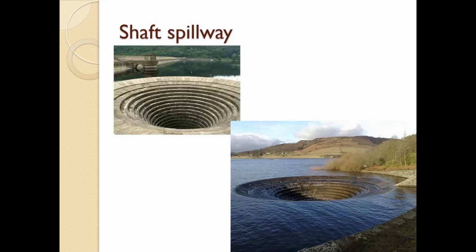The discharge through a shaft spillway does not increase at such a high rate as it increases in weir type spillways. Hence, if an unestimated high flood occurs, the shaft spillway may not prove as useful as a weir type spillway, such as an overflow or open spillway. Hence, the shaft spillway design should be much more conservative than the other types of spillways.